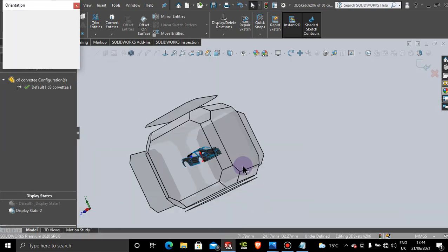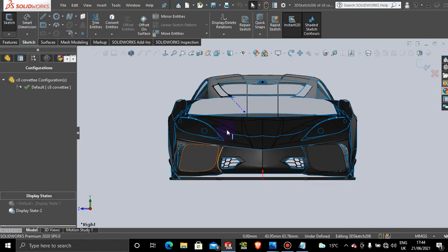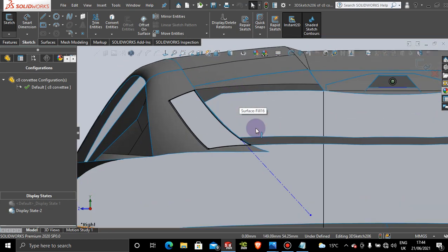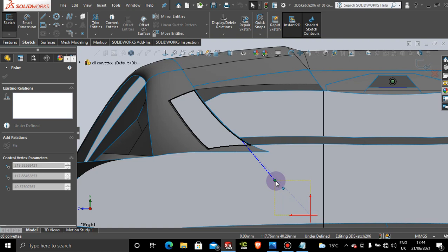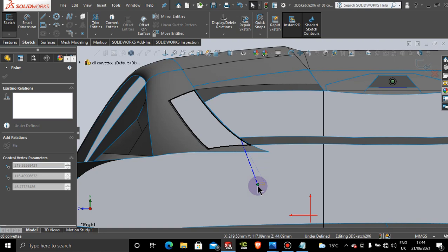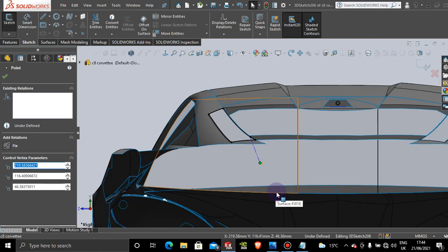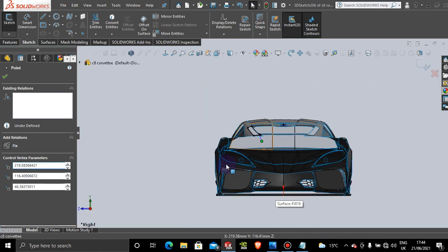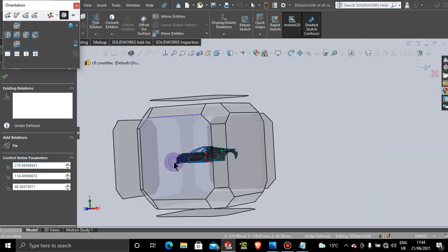And then let's go to spacebar. So let's create that extrude direction. I want the extruded direction to be a bit at an angle, something like this one, not really straight down. So let's create a little bit of angle on that, and let's have a look from the side.